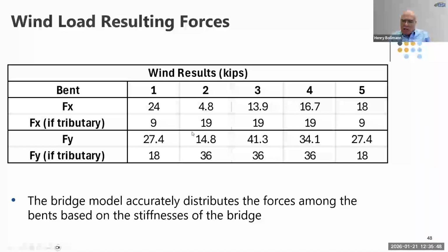So because we've done this now, we see the forces going to that pier, we might be able to use 24-inch piles everywhere on the bridge, possibly. On State Road 105, the 24-inch piles didn't work. But after doing this analysis, I didn't have the bridge model back then, but used other approaches to get this information.